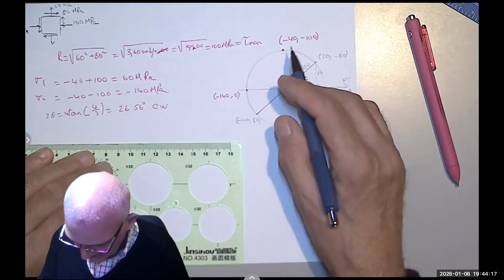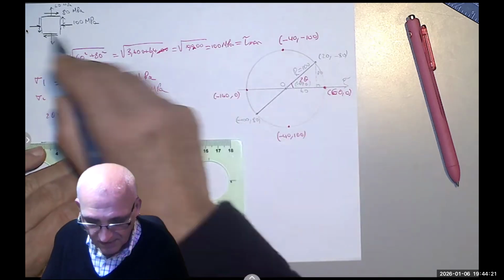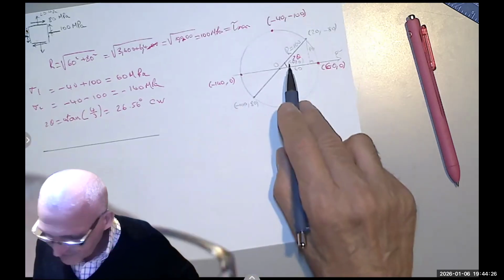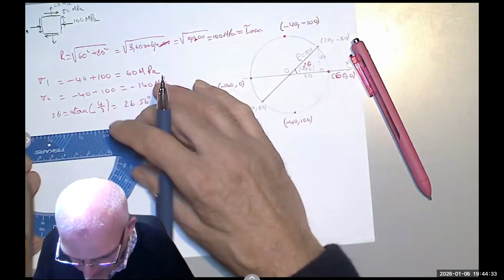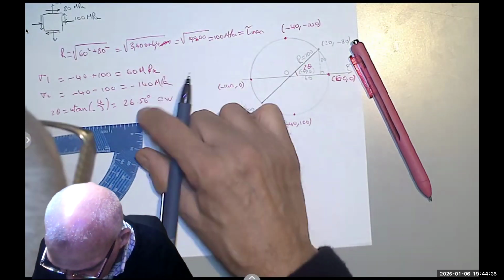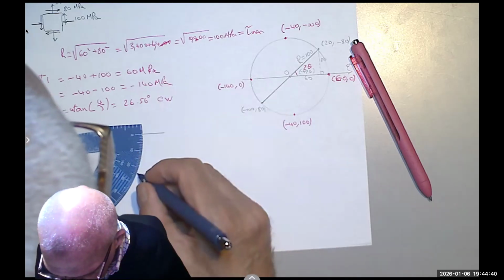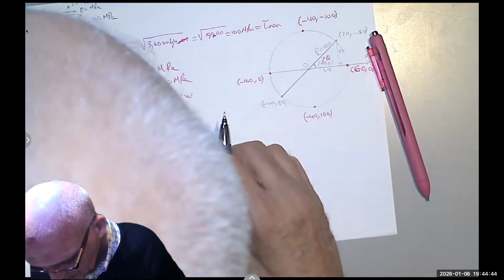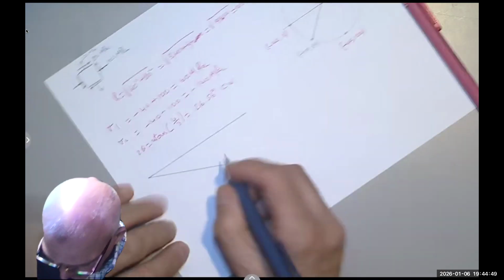So if this is the case, we have here. Then in order to get to the principal axis, I have to rotate an angle of 26.56. That's what we are going to do. We're going to rotate from here. Let's put this on the line. 26, and I have somewhere here. So these are one of the principal axes.